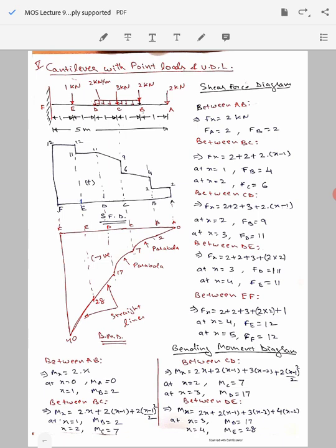So this is the kind of shear force diagram that we will obtain here. We see there are straight lines in this shear force diagram, but there are horizontal lines and there are inclined lines. These inclined lines appear wherever there is a uniformly distributed load, which shows the dependence on x because of this uniformly distributed load. So these ramps appear in this portion and this portion. Elsewhere we are going to get only horizontal lines in this diagram.